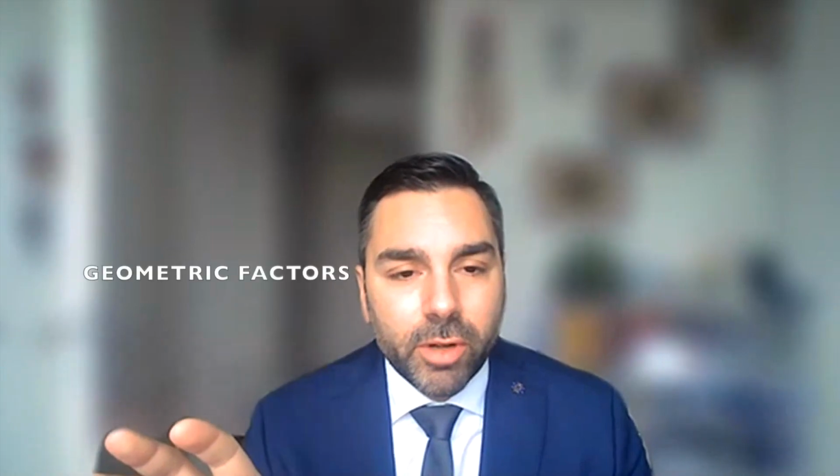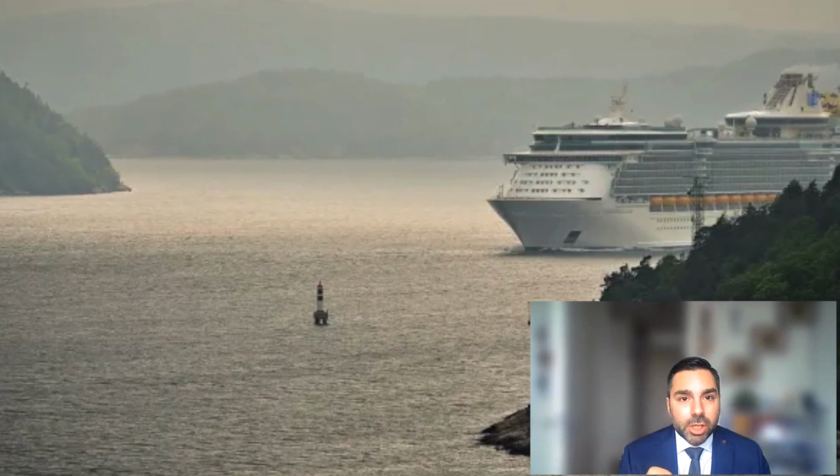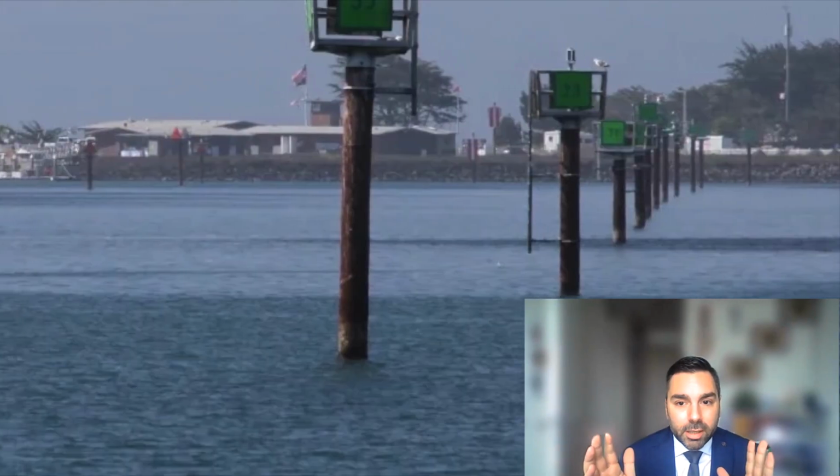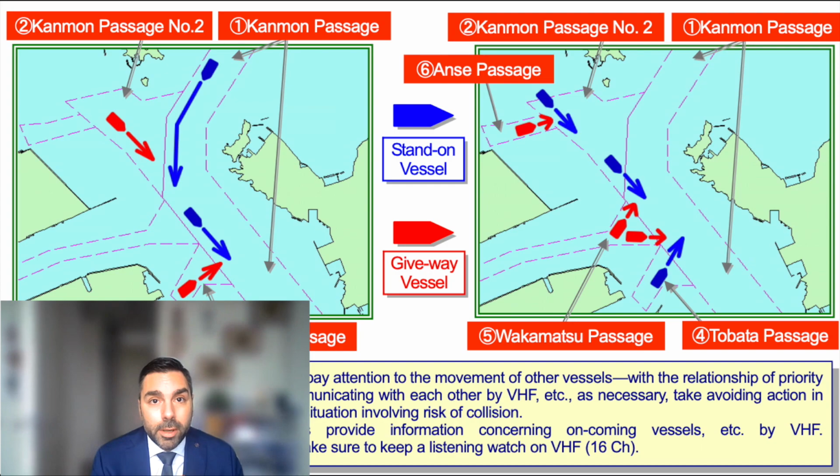There are many factors that affect navigation in narrow waterways. I usually categorize them into geometric factors, such as the width of the channel, the depth of the channel, and any constraint due to buoys or channel limits. Traffic is another concern that we have to keep in mind. Then there are meteorological and oceanological issues such as, of course, wind, current, and so forth. Ship design, equipment faults, and human-related factors also matter.